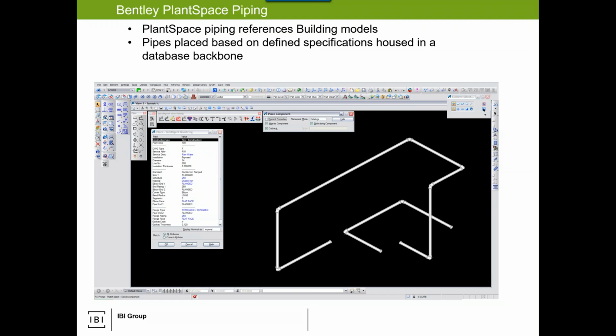And remember that in the piping world, anything we model is dependent on its ability to get to site. So if I model a 50-meter long pipe, that means I need a 50-meter long mode of transportation. So a 50-meter long rail cart, I don't know, I guess a pipe can span multiple carts. What if it has to be tractor bed driven? You have a limitation there. So if there's no rail network that goes straight to your site, a 50-meter long pipe is probably a very bad idea. Hence, you flange it and you think about spooling lengths.